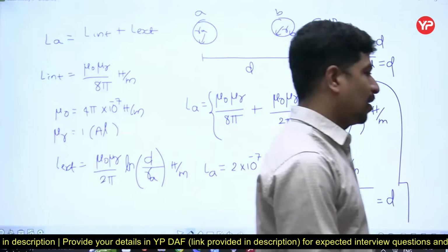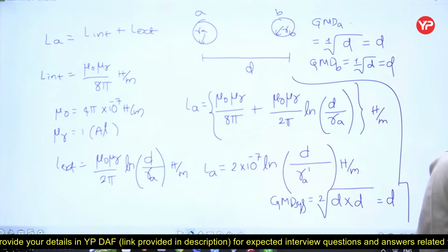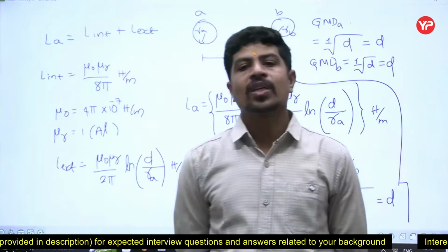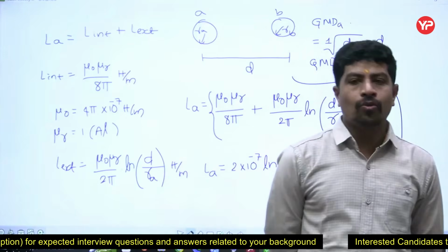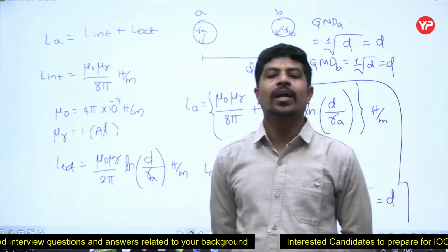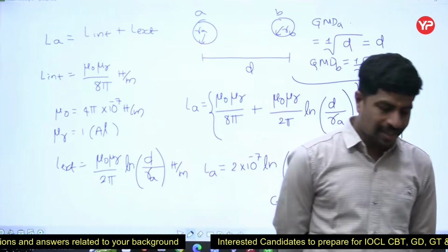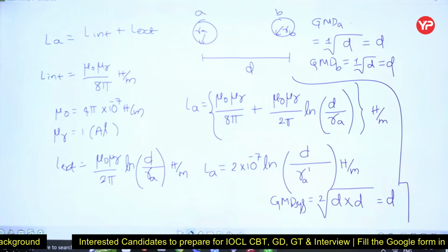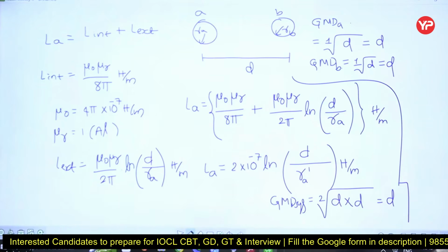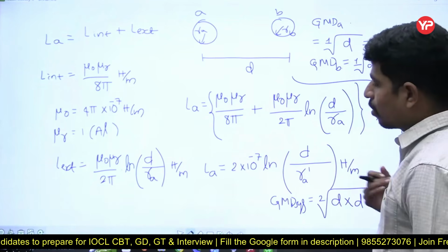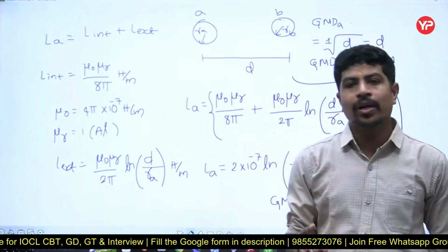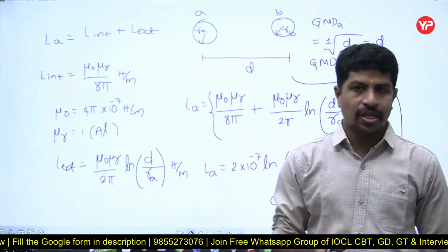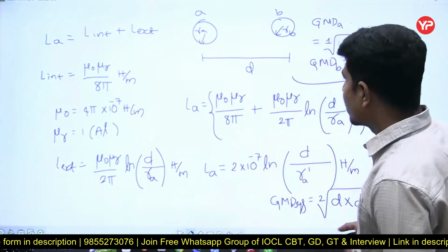What is power system conductor? I told you that we are using ACSR conductor, aluminum conductor steel reinforced. We are using standard conductor to reduce the skin effect. Number of strands also we discussed in the last class. That is a number of layers. First layer is 1, then 6, then 12. That way we discussed, right? So it is always very important to be in touch with the previous discussion. Then you can understand very easily.